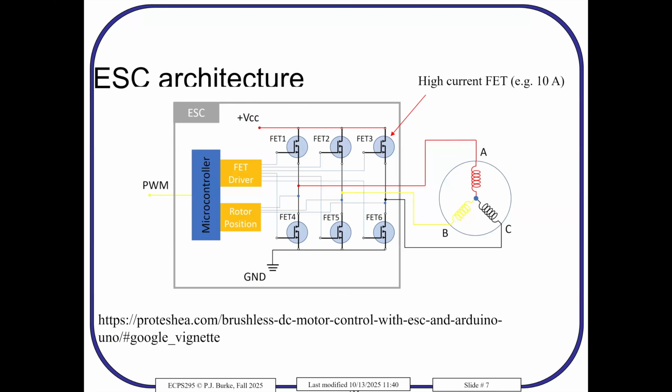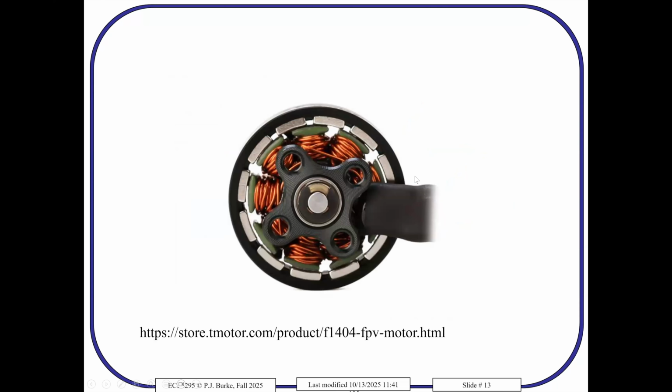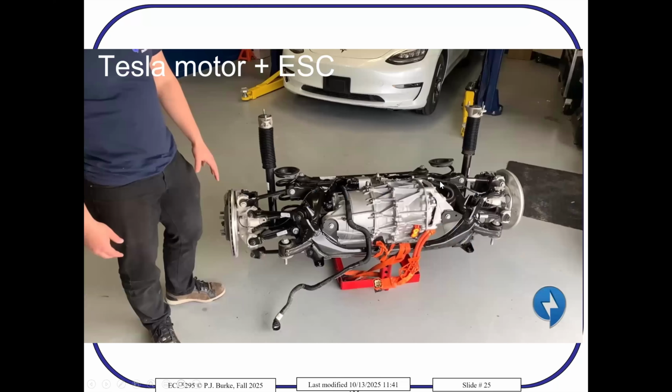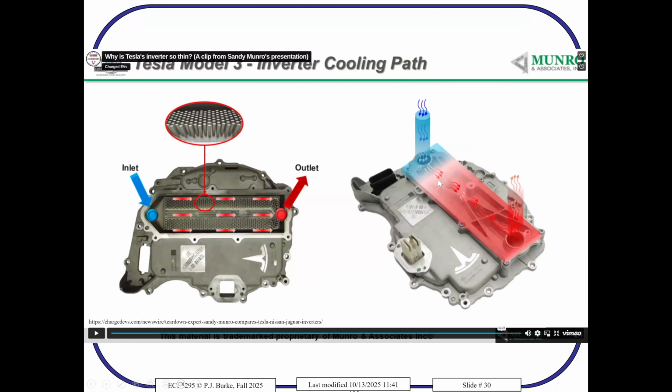Now, it's not that bad because it's probably not 1 ohm. Maybe it's 0.1 ohm or 0.01 ohm. Still, 1,000 watts, 100 watts. 100 watts is a light bulb. Imagine grabbing a light bulb and your hand burns, right? Now imagine putting all that power into one single discrete transistor. So they get hot and they need to be cooled. So the Tesla speed controllers have a water cooling system to cool those power MOSFETs because they're not perfectly efficient. So there's a water cooling system in.